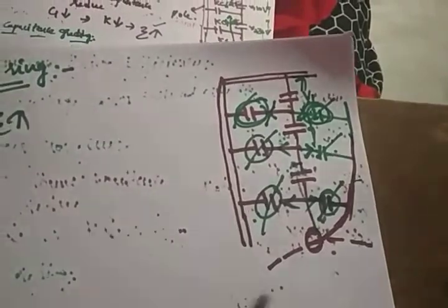So that's why we are placing a guard ring at the bottom of a metal sheath. Alright, you will see it in real life also. If you want to, you can go and see the guard ring, how they are placed, at the bottom of suspension type insulators. You will directly see. So these are the methods to improve the string efficiency. And one important thing that we need to remind is very, very important.